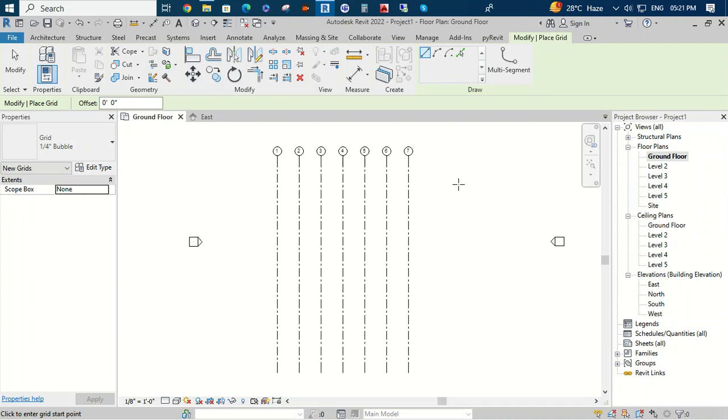the horizontal grid lines. Now you see this, I'm going to start from the right, first click and second click. Always remember to start with line tool to place one reference grid, so that when you use the pick line, it takes this as a reference to offset the other.